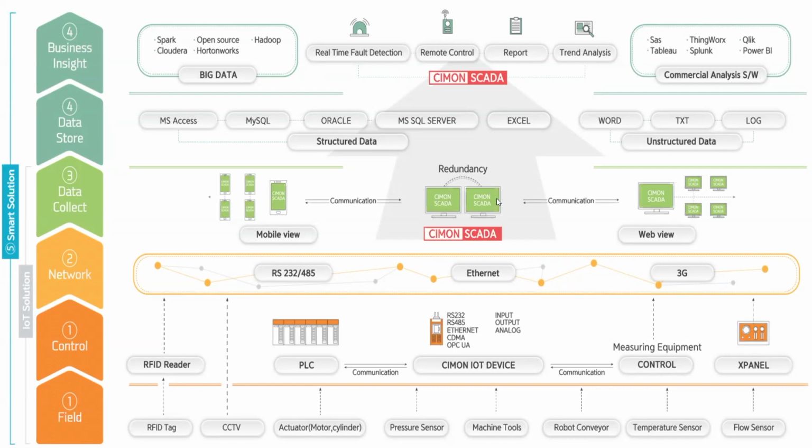We're sending data to the SCADA software where it will control, I don't know, upward of 50 different stations. It just depends on your application. Personally, I have used SCADA software to control 32 different locations, and you just do this with one SCADA software. It congregates all of that data, so it helps provide analytics that you just wouldn't get with an HMI. So an HMI, at the very essence, is a historian device. It can create a data log or alarms and trending for you, but it doesn't really perform analytics.